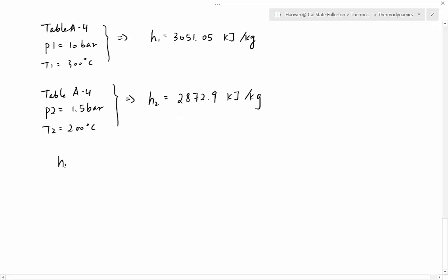There's only one way to do it. If it is a mixture, you have to use this weighted average equation. Can you memorize this equation? Point 2s is a mixture, so it has two components. They are saturated liquid, f point, and saturated vapor, g point.